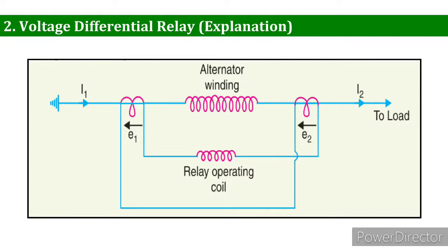This will not happen. This is according to our setting. The setting is basically our predetermined value, so the relay has to exceed that point to operate.